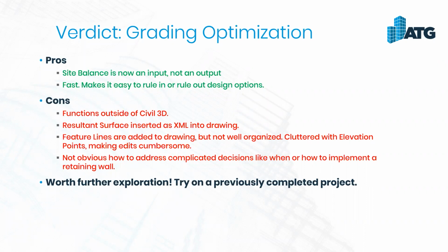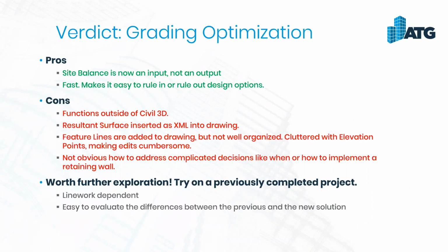The best place for you to test this is on a previously completed project. That's going to give you a good reference point for where we ended up as our human brains for that whole workflow and how this tool came in. And if we can say, oh yeah, well, we needed a retaining wall, but this tool may have given us a way to do not a retaining wall, lessons learned that we can work on for future projects. Just remember, this is a tool that is line work dependent. We have to do our 2D layout in order to use this tool, but we had to do that anyway for the rest of our 3D stuff. And it is really easy to evaluate the differences between that previous and the new solutions.